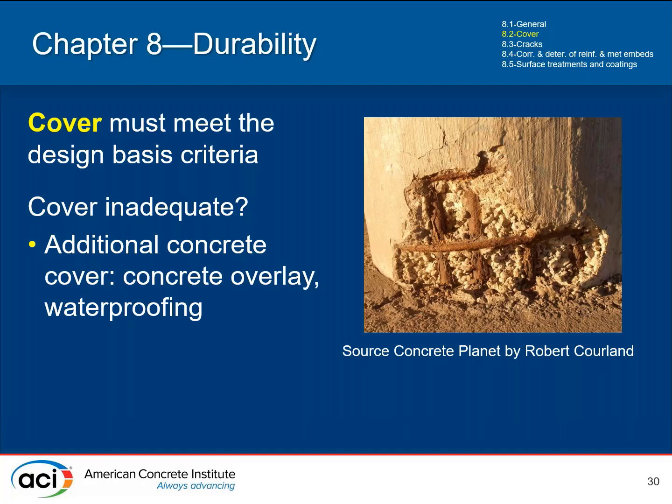The steel was put in the wrong spot, or it shifted during placement, those kinds of things, and you end up with basically zero cover in these locations, and that's why you're repairing it. Essentially, you have a structure that didn't meet the design basis cover, so it's undergone deterioration. We need to fix it. And one option would be to throw up your hands and say, well, it is what it is. This is what we're having. We're going to just get on the cycle of it's not going to be durable. We're going to have to fix it almost continuously.